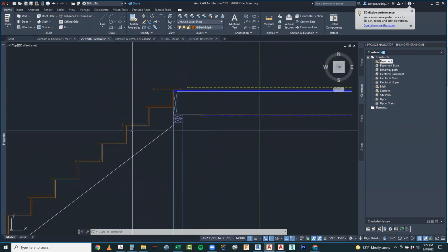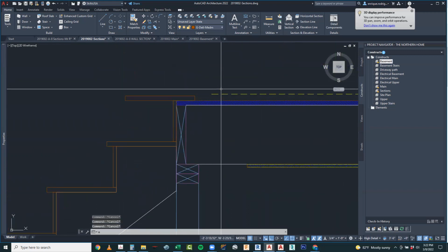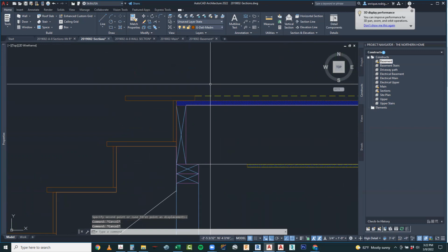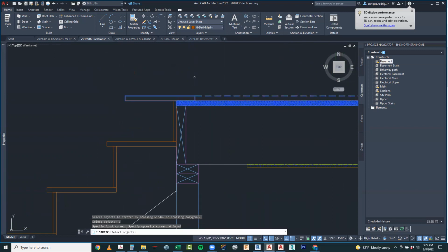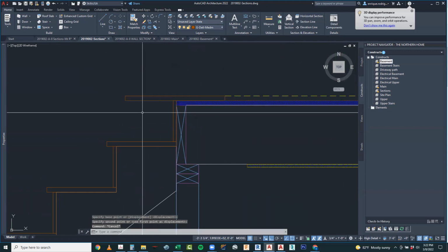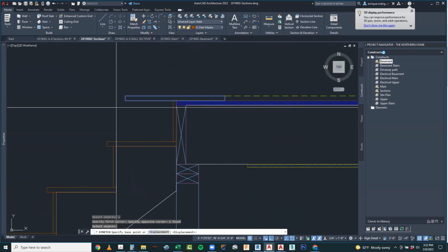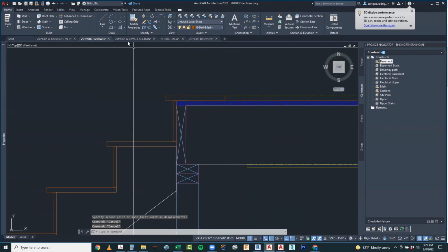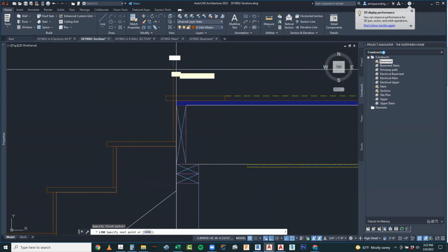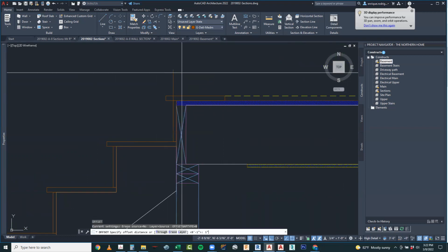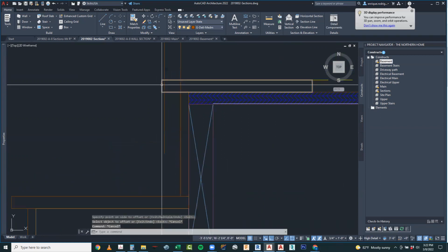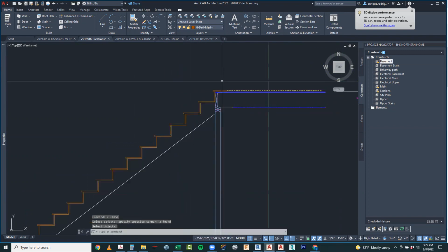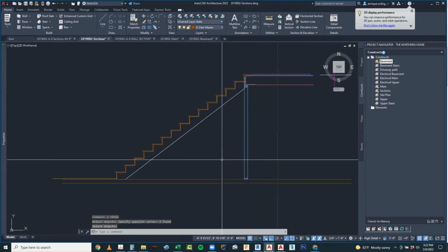All these are just a little bit off. And then this would represent the finished floor at the top. And I can just stretch this out this way, whatever depth we want. And I want to make sure that this distance right here is also 1 inch. I can take a line right here and offset that 1 inch. And just pull this guy right to here. And I basically got my first stair almost completely done.